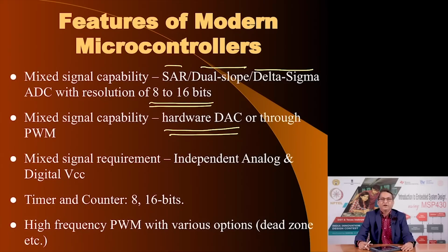Or if it does not have a dedicated DAC, it would offer you that feature through what is called pulse width modulation. We will go into detail on how to get DC voltages or analog voltages out of a pulse width modulated digital signal. As part of the mixed signal requirement, you would see that such microcontrollers have multiple power supply pins